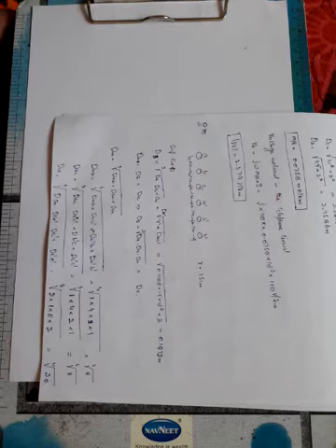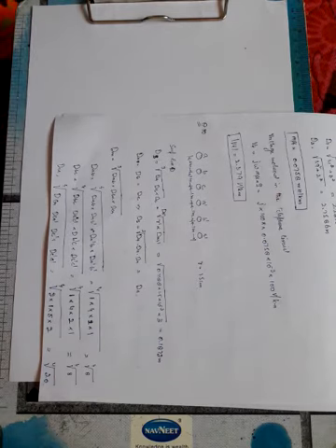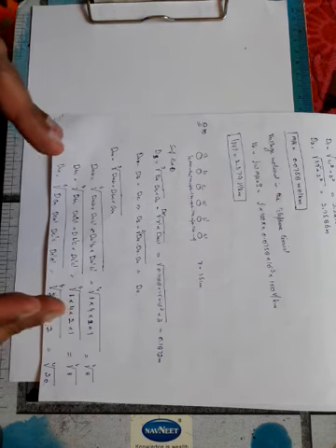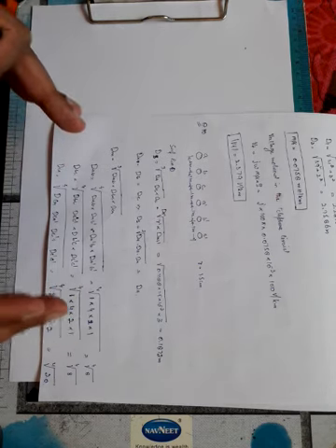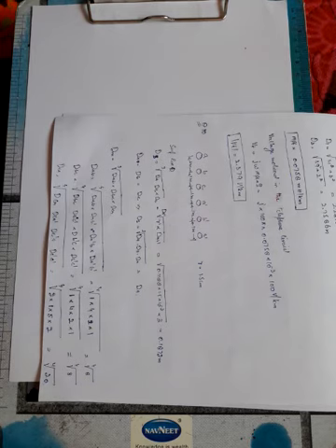And why I gave you this problem, just to make you sure that in case of bundle conductors, the distance between A and A dash as compared to the distance between the phases A, B and C was very small, but in this case that is not the case. You can see they are intermixed, so all the distances ought to be taken care of.